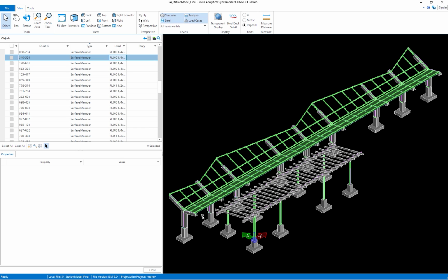So as I'm working with the architect, I'm going to have a very good understanding about what pieces of information belong in my STAAD.Pro model and what pieces of information I'm maybe not necessarily interested in bringing over. For example, I plan on designing my base plates eventually with RAM Connection. I'm not going to bring in the base plates from this particular BIM model. So I'm going to review it from those types of aspects.